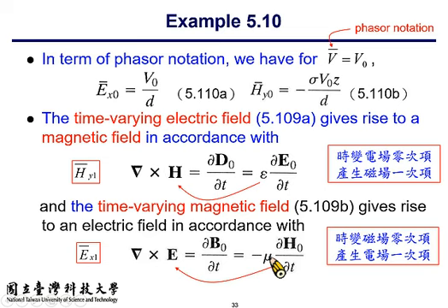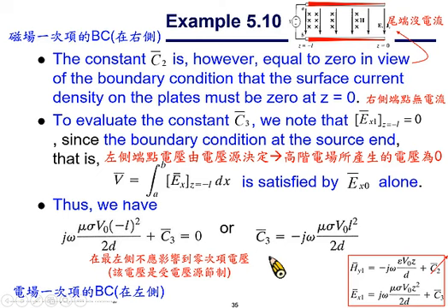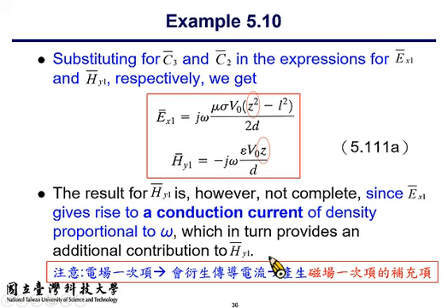However, we should know that because the dielectric has non-zero conductivity, the first order electrical field, EX1, will also produce a conducting current. And this current term shall produce the so-called complementary first order magnetic field. So it's referred to as HY1C, the complement term.